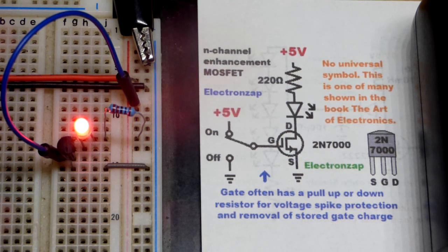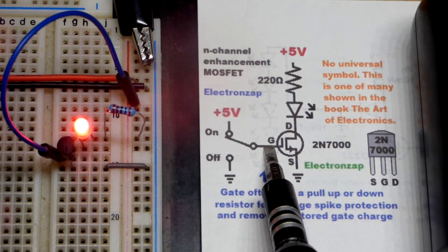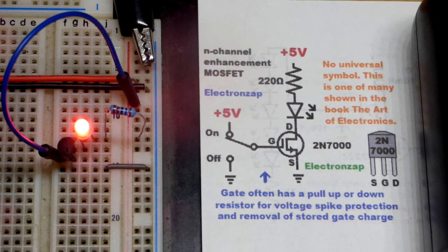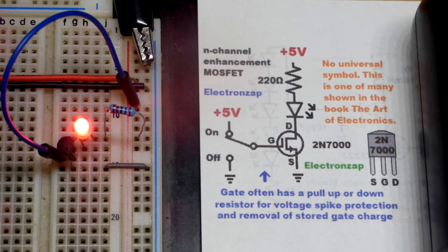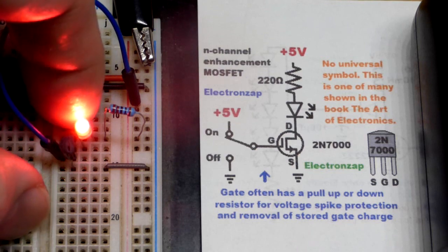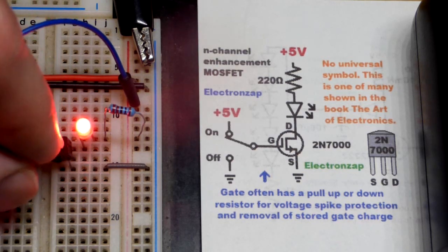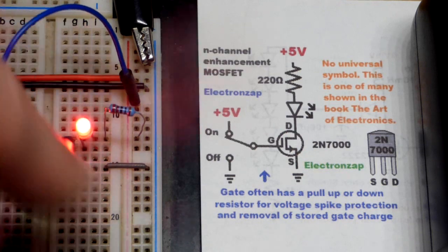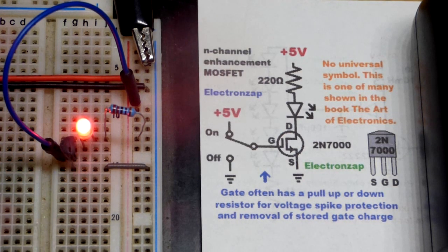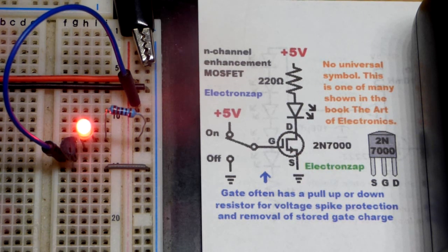So this is very energy efficient. We just have to give it the proper supply voltage to the gate. At that point, that's not using any current. Now all the current is going through the LED, or load, right there. So we're not wasting any, I forget what the name is, but there's a name for how much current something has to use just to maintain itself. That's not current going through the load. Is it quiescent current? I can't remember. But this doesn't depend on current flowing constantly through it for any other current other than what's going through the load. Load is getting all the current. Transistor isn't conducting perfectly, but it's conducting really good. For the most part, it's the resistor setting the current for the load, in this case, at 5 volts when it's powering an LED. Hopefully that makes sense.